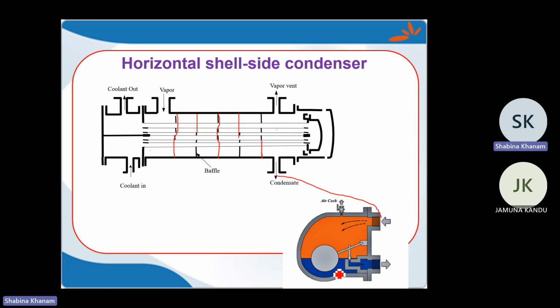But as the level of condensate goes down, only steam would exit, so as the level of condensate goes down, it closes this valve. It brings this balloon down, which brings this valve down, and which closes this opening. In that way we consider the steam trap, which is an important part. So when I am considering the condenser, we need two additional accessories, that is the vent as well as the steam trap. So that's all.